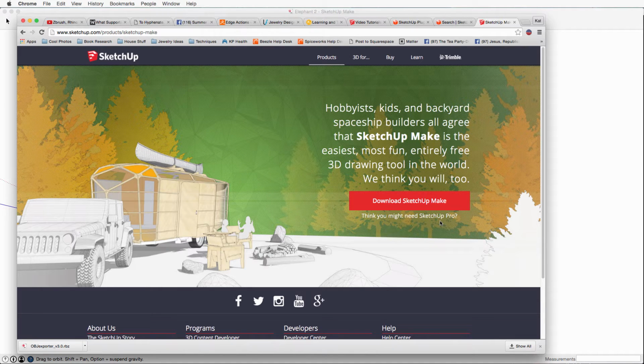The main difference between SketchUp Pro and SketchUp Make is some solid modeling tools, which you won't need right now. The other thing is Pro has all of the exporters for 3D, so OBJ, STL and DWG files can all be generated from Pro, but in SketchUp Make you have to add a plugin. So it's not really a big deal, but SketchUp Make is free.